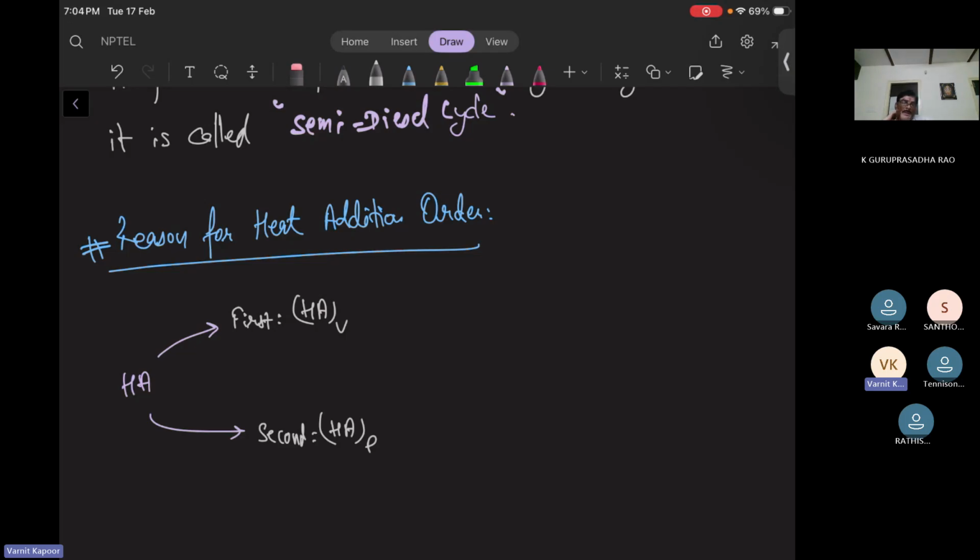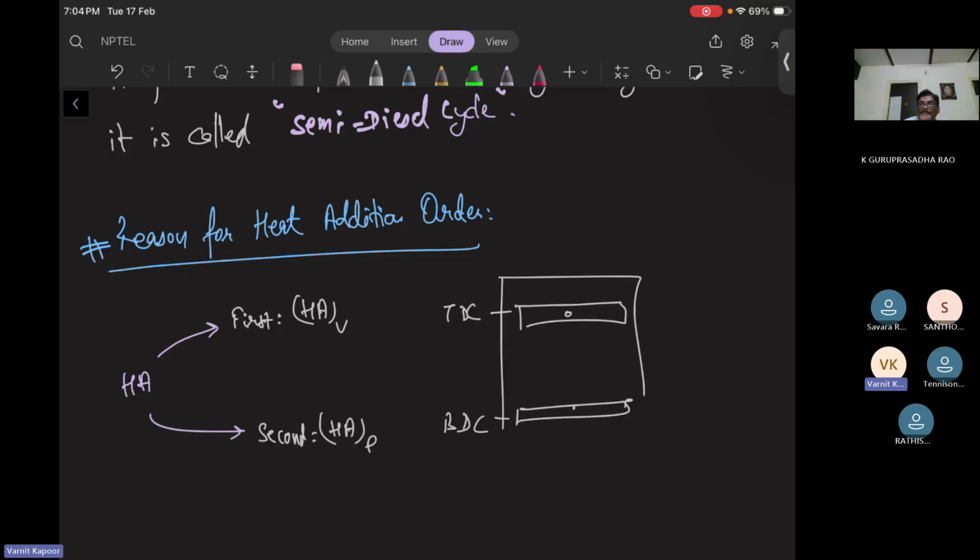Practically, let us understand. Suppose I have a piston cylinder arrangement, and the piston goes from BDC to TDC. Now I am providing some fuel inside it and adding heat, but because of the compression, temperature has been added. If I want heat added at constant volume, my piston should remain in this position, instantly at this position.